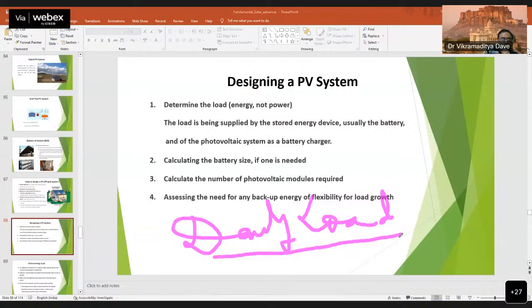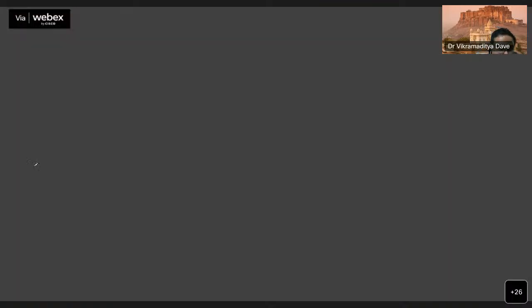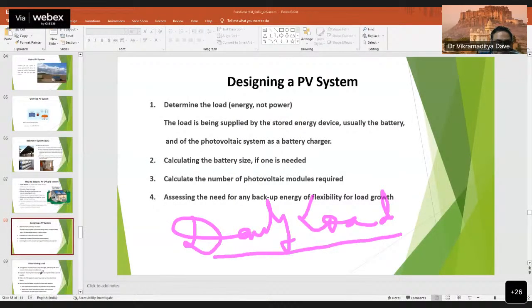So you can go for either 1 kilowatt which runs for 2 hours. If it is 10 units, 10 units means 10 kilowatt hour. So accordingly you have to decide how much wattage of solar PV you have to install according to the load, on the daily basis load, not on the 12-month basis load.